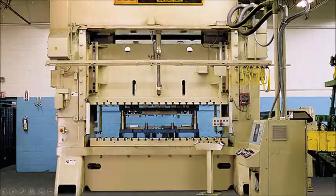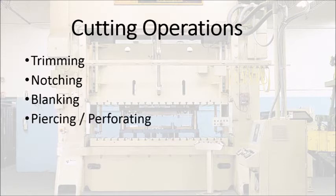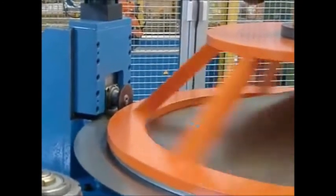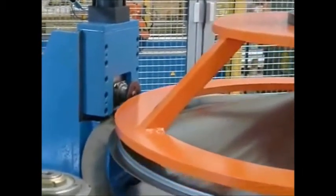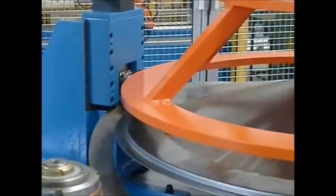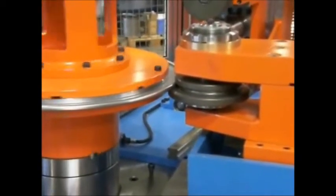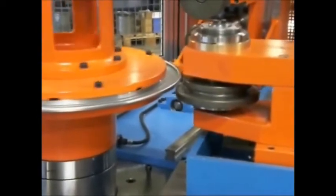Such operations include trimming, notching, blanking, piercing or perforating, lancing, and nibbling. The most basic type of cutting is trimming. Trimming is used to cut away the unwanted confines of the metal to shape it into a more defined structure. For example, when a piece is badly cut, trimming is required to remove the non-essential parts.